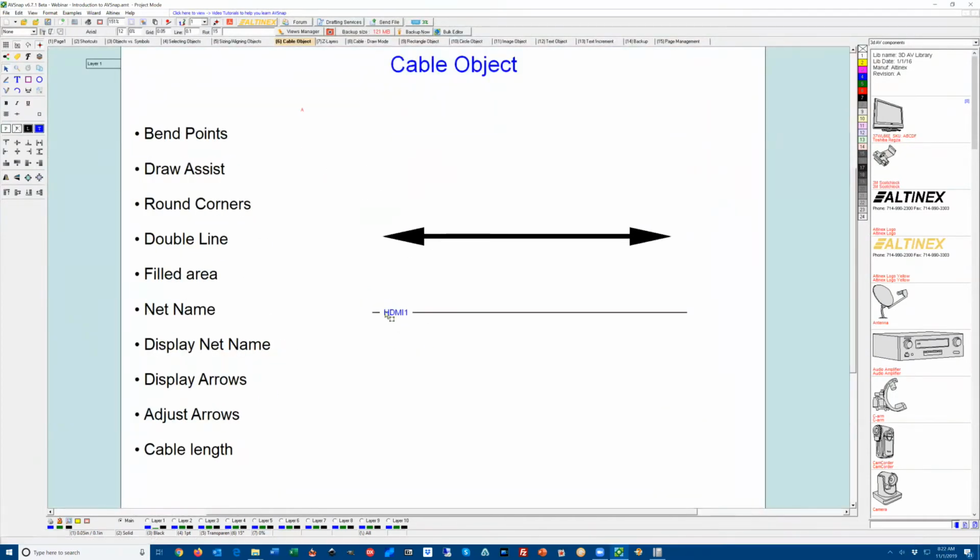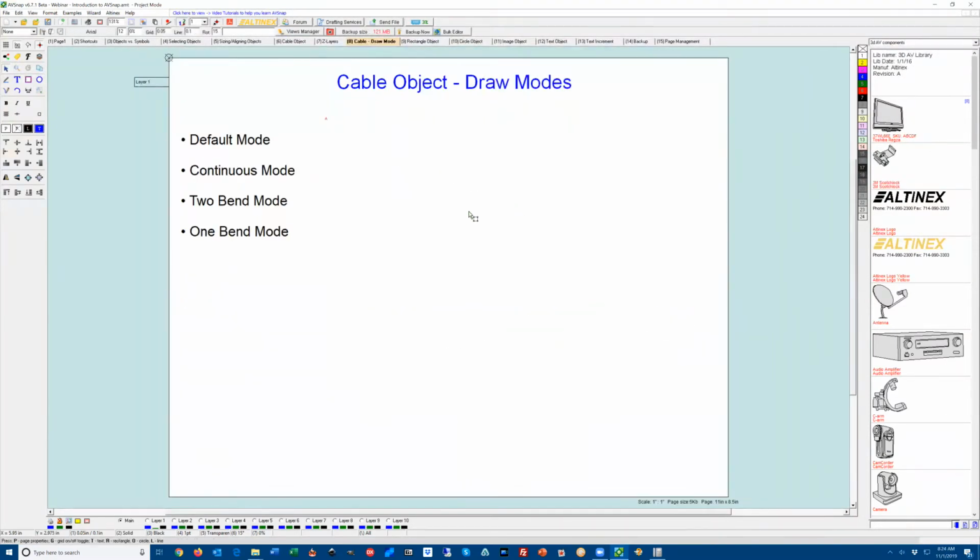So this is on the beginning of the cable. If you press period, you can do the same thing on the end of the cable. The normal way of drawing cable is to draw cable and continuously draw cable by putting your mouse pointer to the end and have it captured by the end of the cable. But in many cases, this is not convenient because you have to press the mouse key every single time you need to draw a different segment on the cable.